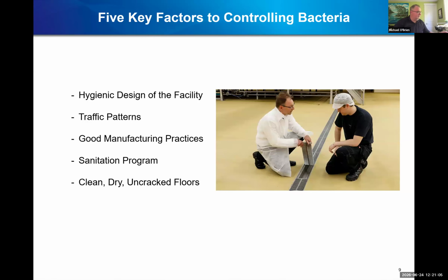So 5 key factors to controlling bacteria in a food facility is hygienic design of the facility. So you have to be able to clean everything, all the equipment. You won't see stuff coming down to the ground that you can't get under and clean underneath the equipment. Traffic patterns. So you want to make sure that you don't have raw materials traveling in or around areas that